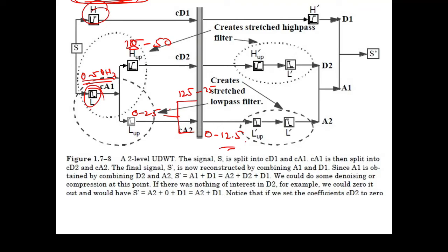Okay, suppose you could fine tune these things, say your ECG signal is corrupted with 60 Hz noise, power line interference. For removing the 60 Hz power line interference, you would have to remove the frequency components from 50 to 100 altogether. That means you are removing a considerable amount of frequency components from your ECG signals.